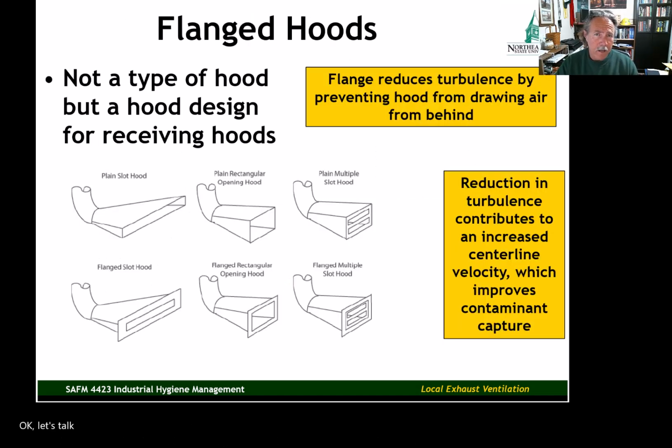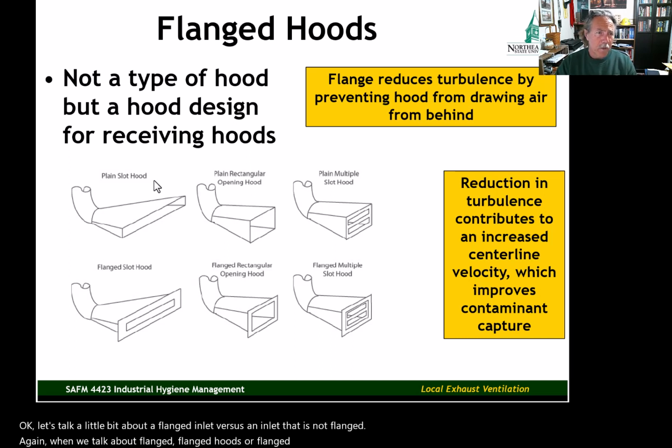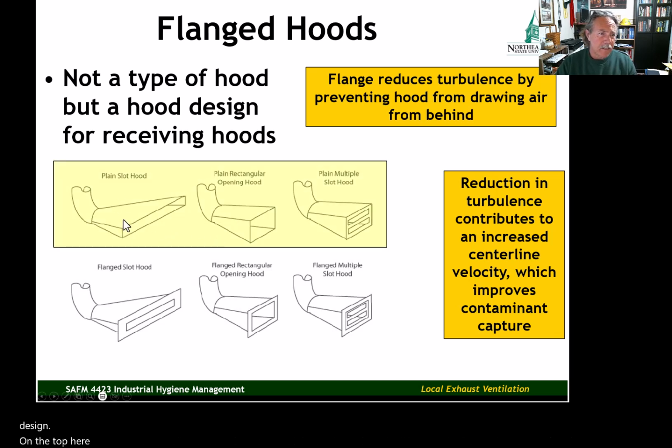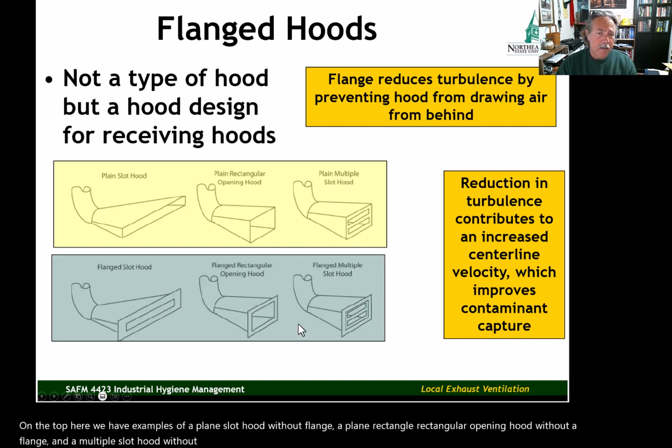Okay, let's talk a little bit about a flanged inlet versus an inlet that is not flanged. Again, when we talk about flanged hoods or flanged inlets, we're really not talking about a type of hood, but a hood design. On the top here, we have examples of a plain slot hood without a flange, a plain rectangular opening hood without a flange, and a multiple slot hood without a flange. In the lower diagram here, we have the same designs with the addition of a flange.